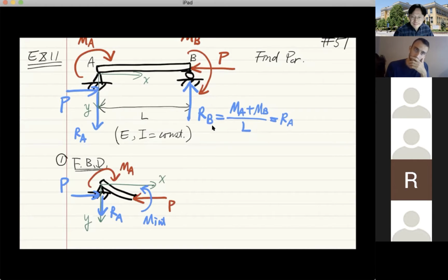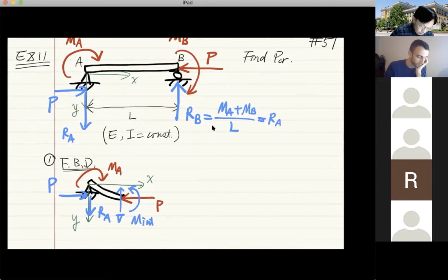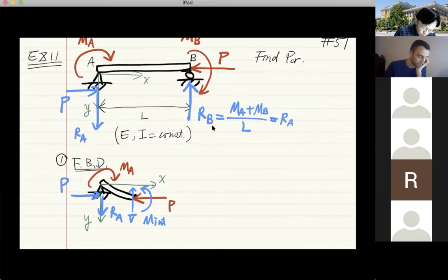Do we have shear? Yes, of course. And in this case, what's the direction of shear? Up. Goes up, right? And so this is your shear. And that's the complete free body diagram. Once you arrive at this step, everything else will be relatively easy. And then we can just write down the summation of moment to be 0.